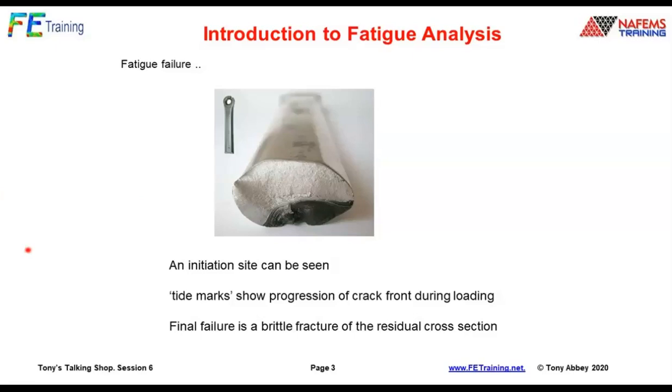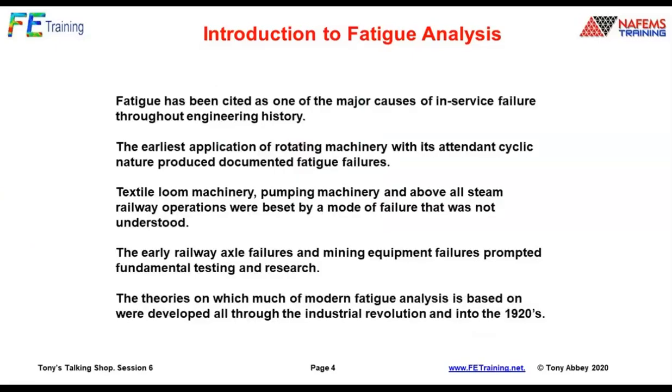So there's a lot to think about in the way that we separate these things out. Fatigue is cited as being one of the major causes of in-service failure, associated very much with rotating machinery. As soon as the Industrial Revolution came along, we've got pumps, textiles, machinery, looms, and so on. People started to find failures at unusually early levels.